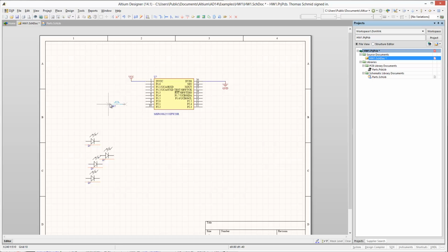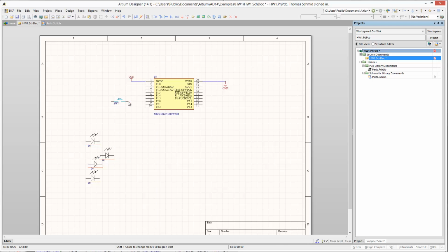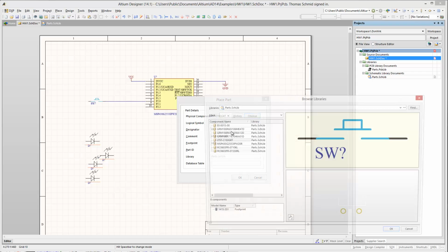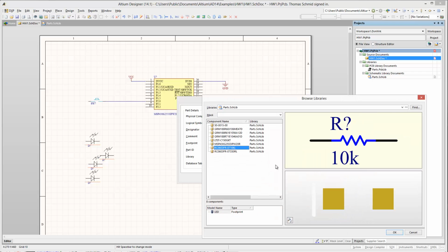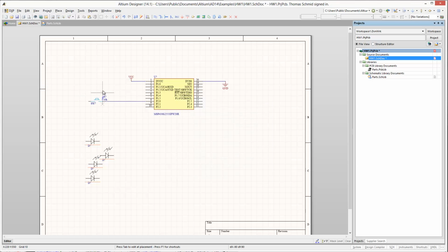Next, let's add the switch. We add a wire to one of the pins. This will be the pin that when we press, there will be a different signal over here that happens. And what we want to do is that the pin is by default high. So let's add a pull-up resistor. Let's choose a 10K pull-up resistor that we add in here.